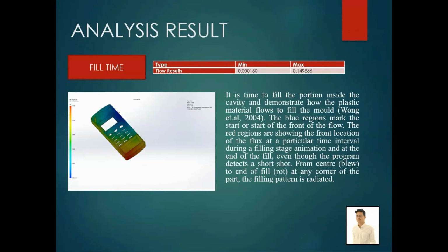Alright, from ZAKWAN, so I will explain and show our result simulation for plastic. Okay, first is the fill time. The result is minimum at 0.000150 second and maximum at 0.149865 second. So the fill time is to fill the portion inside the cavity and demonstrate how the plastic material flows to fill the mold, by Wong et al. 2004.